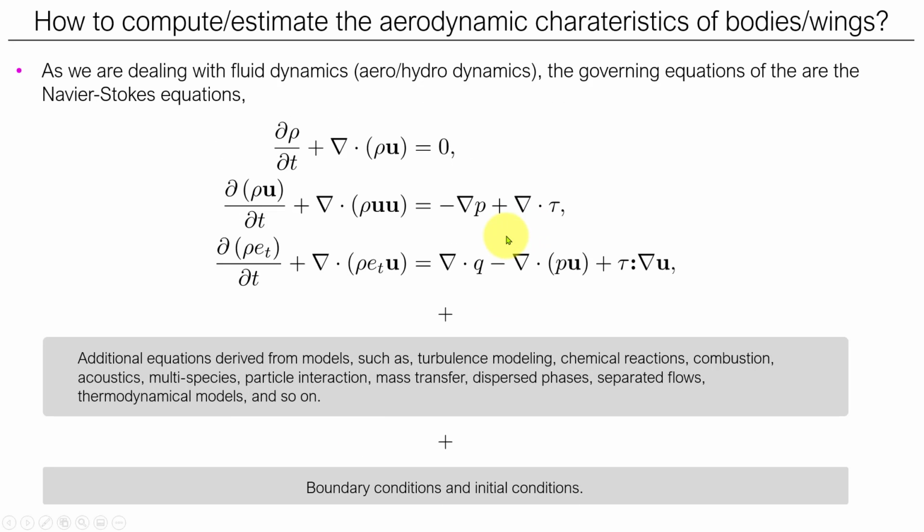So the equations that we're solving are these. Okay, so these are the equations of fluid dynamics. So we're talking about aerodynamics. Navier-Stokes equations are able to predict very well the behavior of fluids. As you see here, they look difficult, and they are difficult, as I mentioned, but not only do we have this set of equations, plus this one we have many closure models. So those things that we cannot resolve directly with this, we resolve using models. The most well-known model is the turbulence model, and this has an incredible effect on your final solution, and it's very important to take it into account. So behind this one there is another theory. There are many turbulence models.